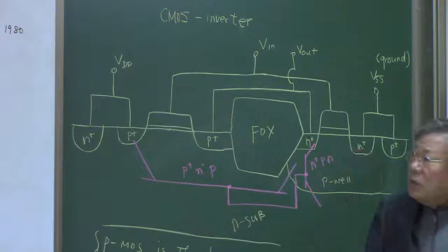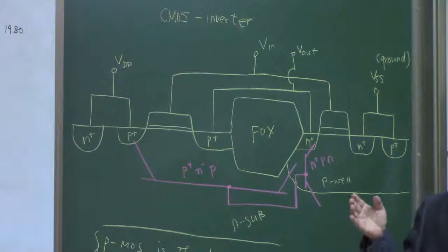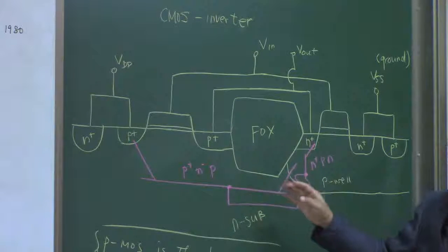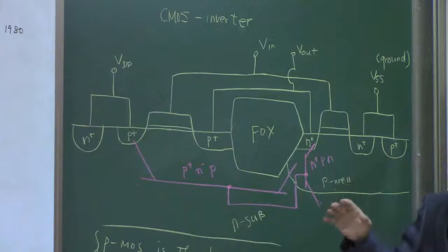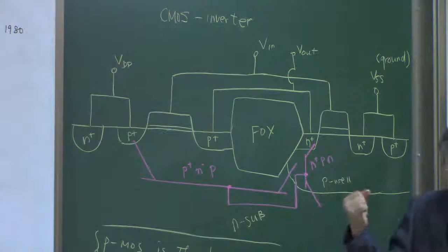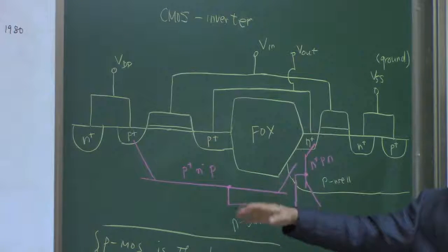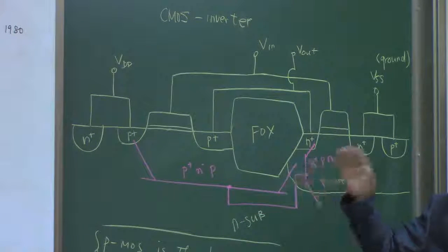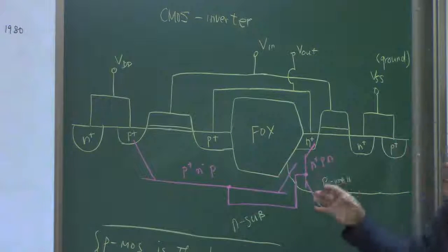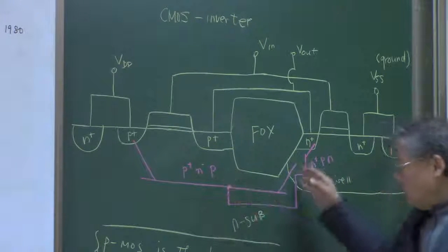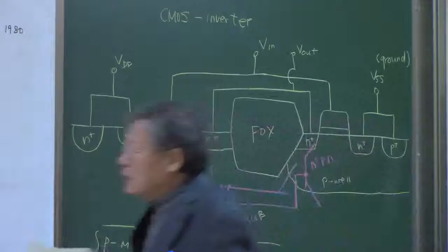So the latch up process itself is not going to ruin the device, but the resultant heat is going to destroy the circuit. So the current induced heating is the problem. We have to prevent somehow this triggering process.